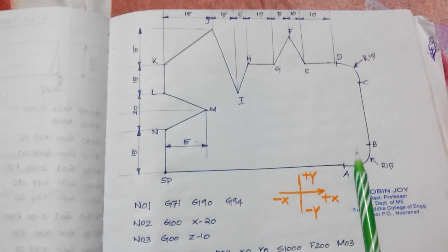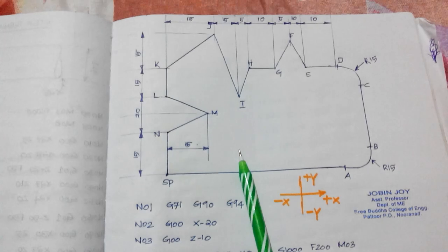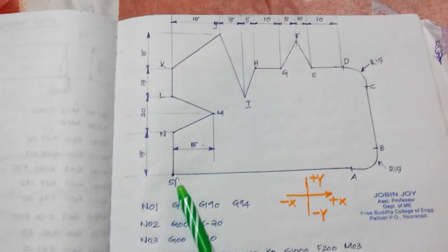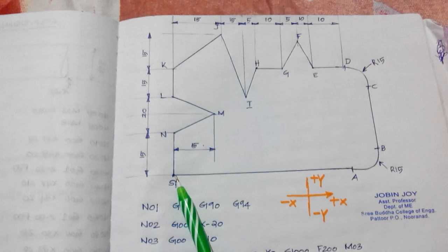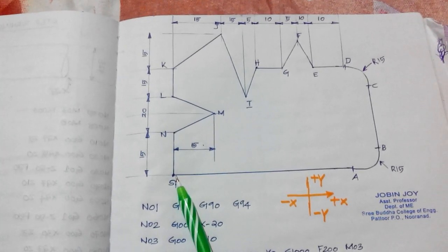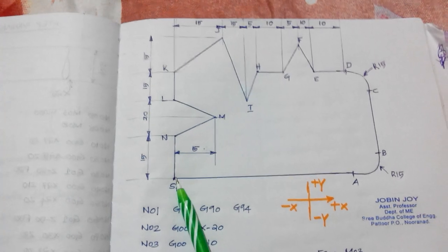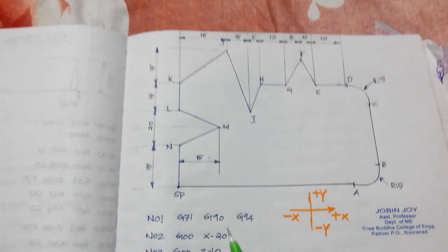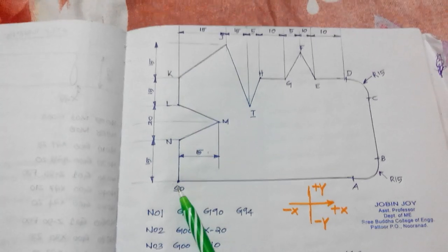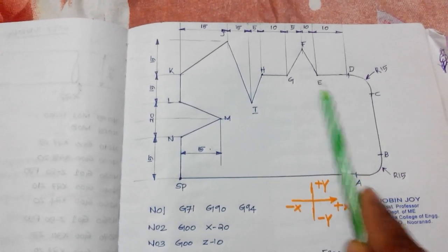And the surface of the workpiece is set as Z0, and the downward movement is Z negative, which means depth of cut is negative, and Z positive means the tool is retracted from this surface. So the tool is moved from this starting point to A, B, C, etc.